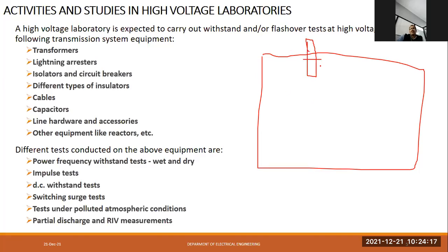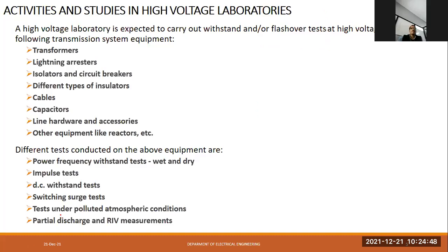There is even a board, and on this board you can see how many times a lightning stroke has occurred. If there is lightning several times, it will measure how much voltage has been generated, and how much current was drawn to the earth, or grounded. The lightning arrestor keeps track of all these things. The important thing is that it will ground the excessive current or excessive high voltage. So this is another protective device used in a power substation or power system.